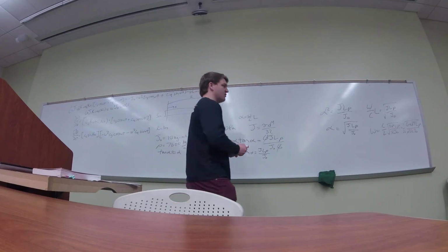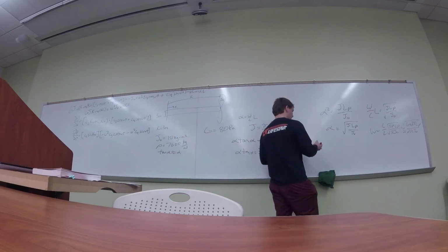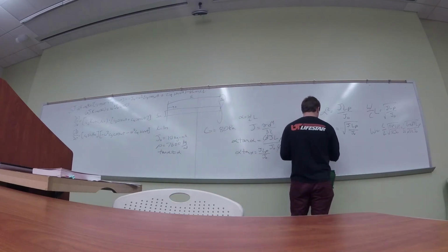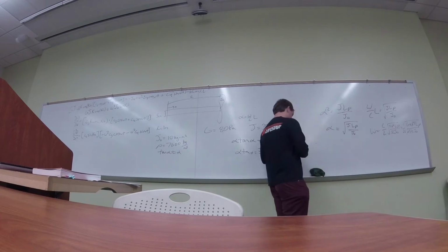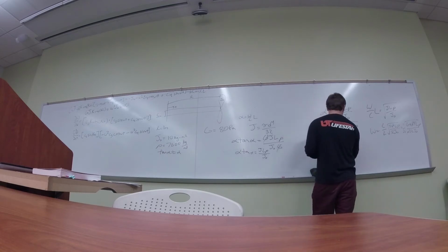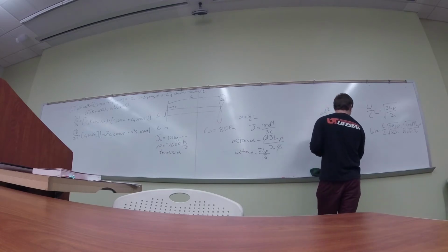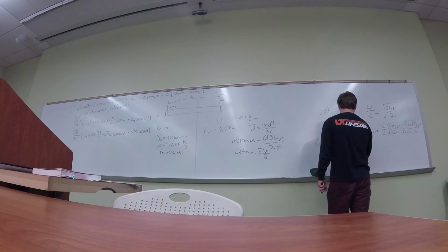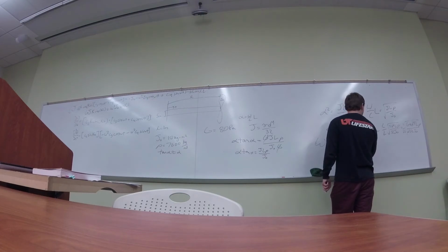So it's going to be some multiple or half multiple of this. And to just continue on, to give you the final answer, omega is equal to 1 over L times the square root of G pi d to the 4th L over 32 J naught.